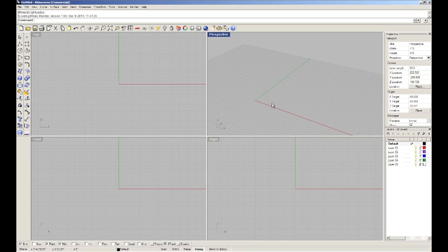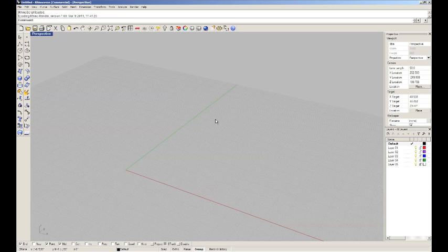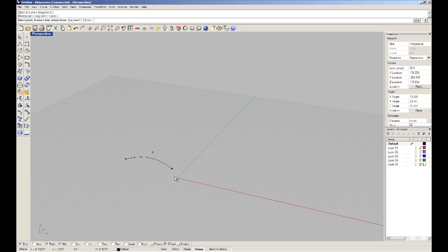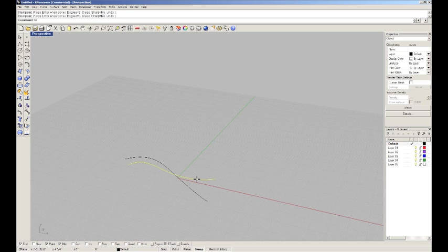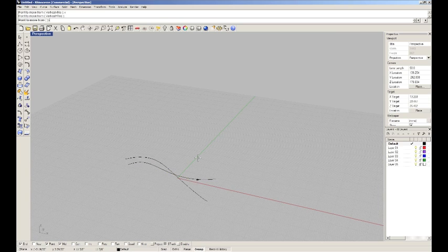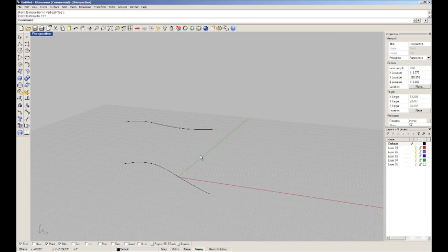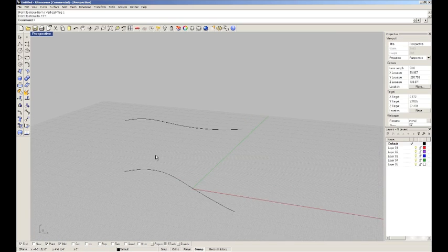So firstly, let's start in Rhino and talk a little bit about something called implicit history, which is the precursor to Grasshopper. So in Rhino, there's a button down here on the bottom called Record History, and we haven't really talked about this yet. But as an example, let's look at what happens when we loft two lines together. So I'm just drawing two curves, and then I'm going to move one vertically, and I'm going to loft the two curves together.